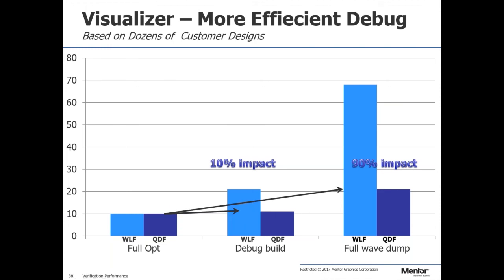So I need to put on that +acc switch so that I can collect all of that data. Just turning on that +acc switch slows your design down by about 2x. So now just turning on that debug, the inefficiencies of the optimization, because I have to preserve all that data, means that's going to run 20 minutes.